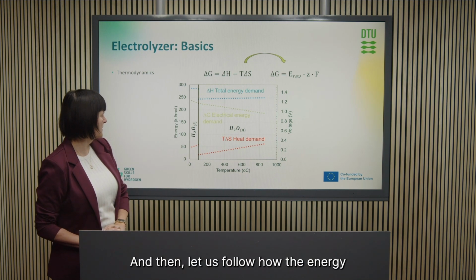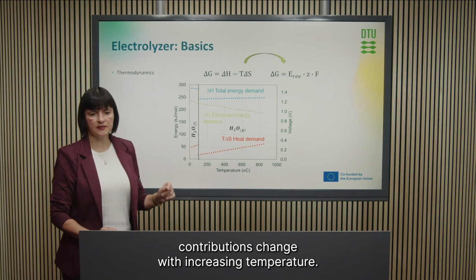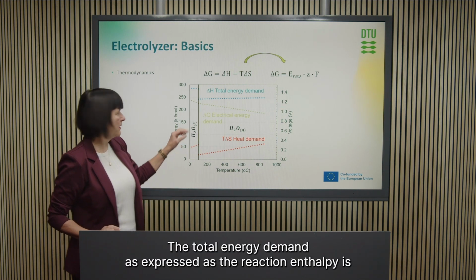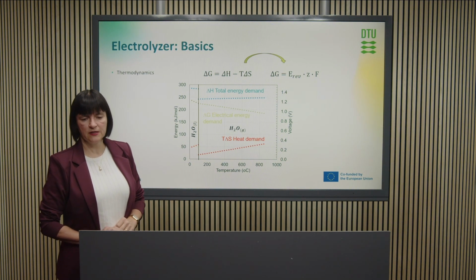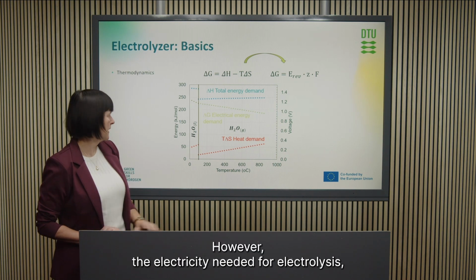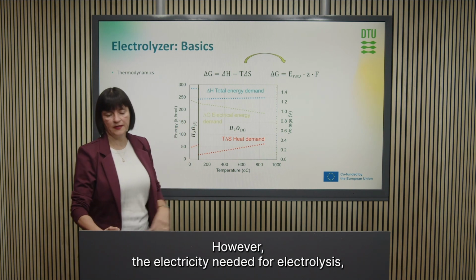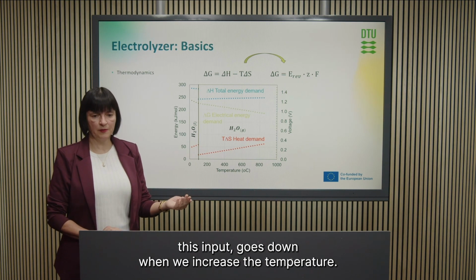And then let us follow how the energy contributions change with increasing temperature. The total energy demand, as expressed as the reaction enthalpy, is fairly independent of the temperature. However, the electricity needed for electrolysis, this input goes down when we increase the temperature.